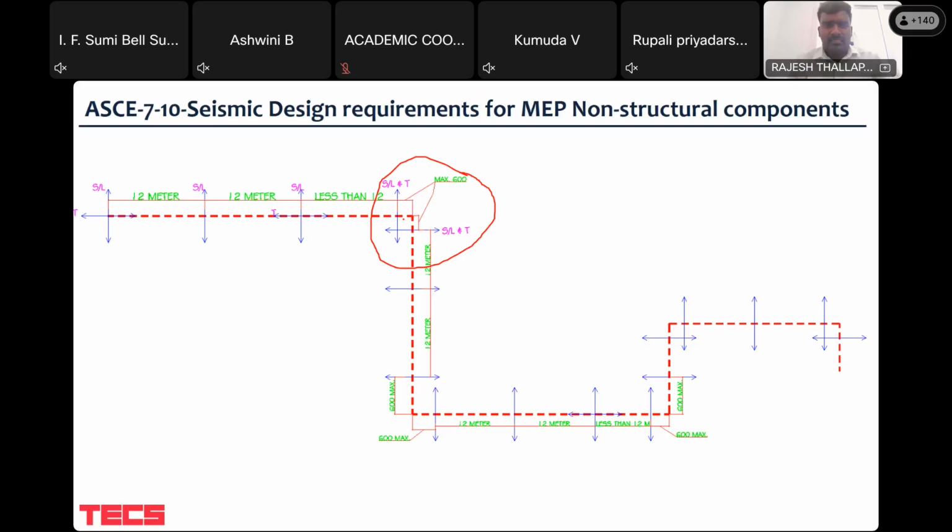So it creates an additional pressure, right? The force will get resolved into two components because the direction gets changed. So which we call an elbow or a joint pressure in mechanical language, I would say. Actually, this is a joint of mechanical and structural subjects. So if you see such locations, these elbows should be protected, means it should be designed for the hydrostatic pressure, as well as when, assume that when the pipe is in operation, means when it is carrying full load of water and there is a seismic activity happen.